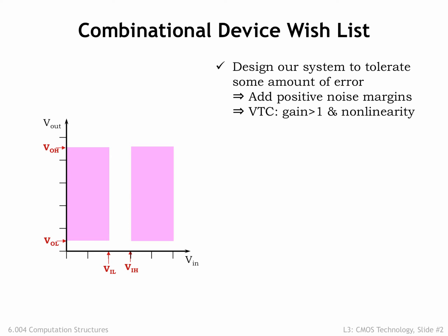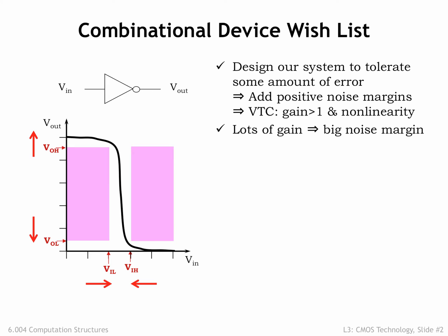The center region, bounded by the 4 threshold voltages, is narrower than it is high, and so any legal VTC has to have a region where its gain is greater than 1, and the overall VTC has to be nonlinear. The VTC shown here is that for a combinational device that serves as an inverter. If we're fortunate to be using a circuit technology that provides high gain and has output voltages close to ground and the power supply voltage, we can push VOL and VOH outwards towards the power supply rails and push VIL and VIH inward, with a happy consequence of increasing the noise margins.